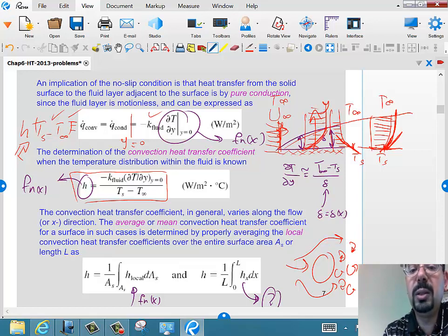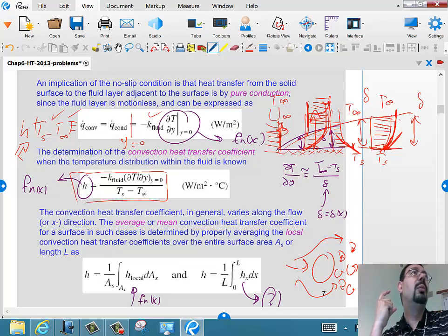So one part will start feeling the wall, while the rest of the fluid doesn't even realize there is a wall there. And that boundary layer thickness gets bigger and bigger as more and more of the fluid starts hearing about that wall, or the viscosity basically starts moving this effect.